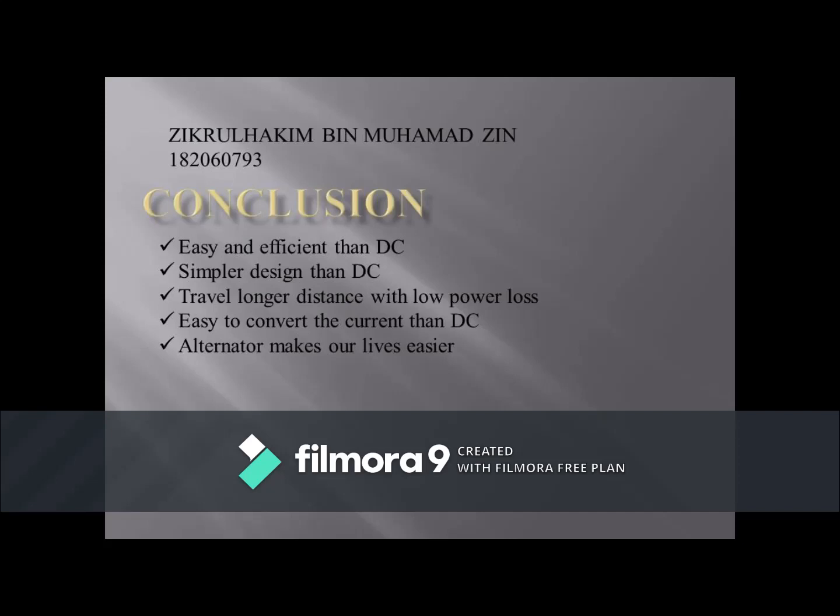And the AC generator is also easier to convert the current than DC because it does not need matching voltage. A DC generator must produce voltage at the level at which it will be used, while AC has the advantage of allowing you to convert the current to a different voltage using a transformer, and a transformer works with AC only and not DC. Finally, the alternator makes our life easier because it is easy and efficient, simpler in design, travels longer distances with low power loss, and is easy to convert the current compared to DC.